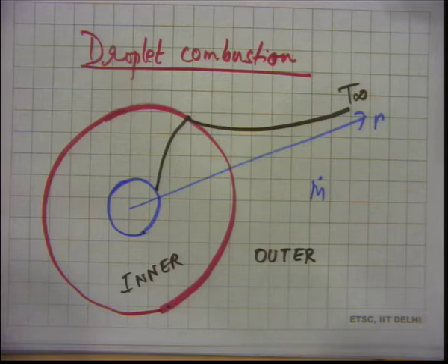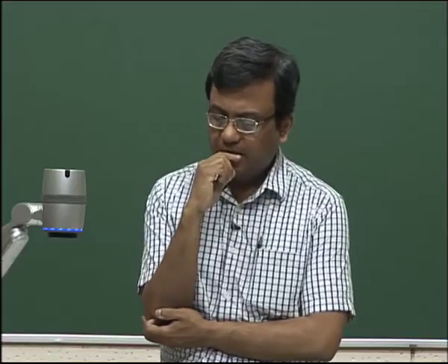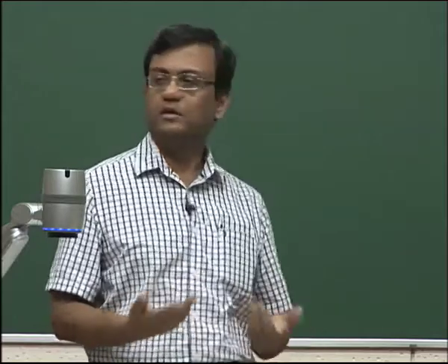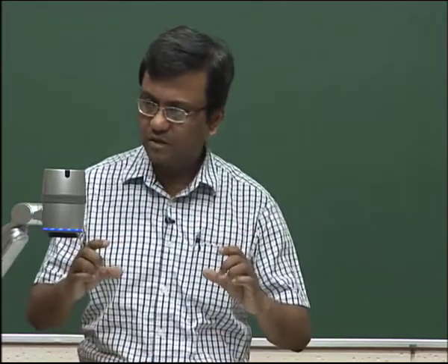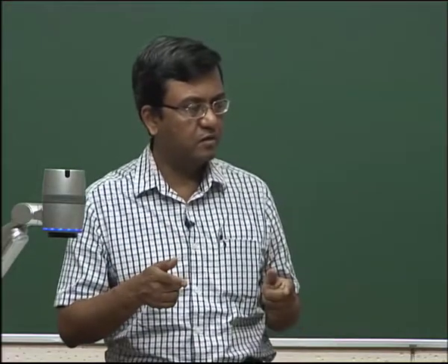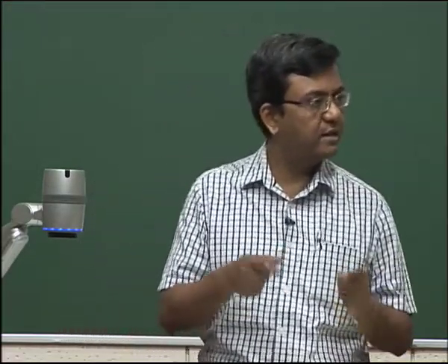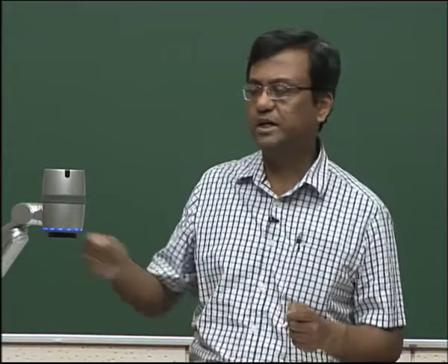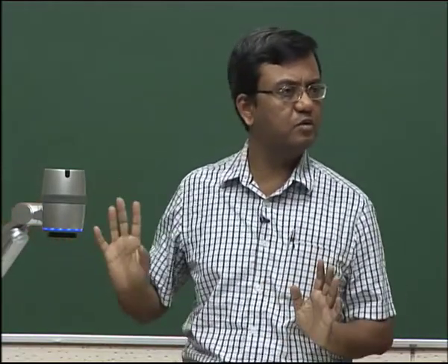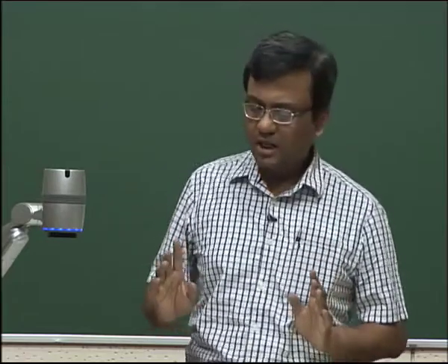Okay, what are the complications that you envisage in that case? Yeah, so now we have reaction. So in that case, energy equation could be solved easily. We had this Shvab-Zeldovich form of the energy equation. Just placed a boundary condition of T equal to T boil at the droplet surface and T approaching T infinity far away from the droplet. These two boundary conditions were fine. But now what is the problem?